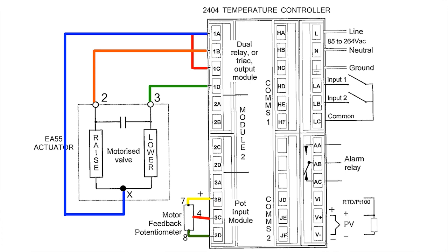Now, when the temperature controller turns on or off, it will provide a relay closure or triac output signal to either move the motorized valve actuator in the clockwise or counterclockwise direction.